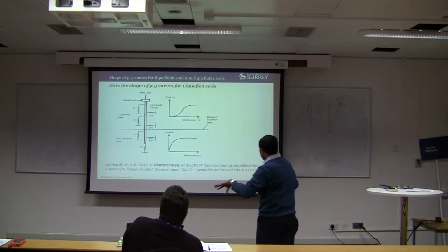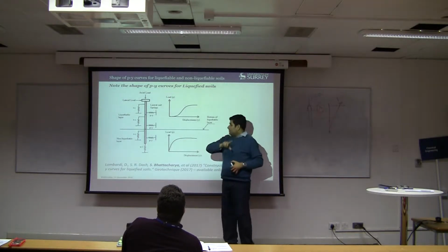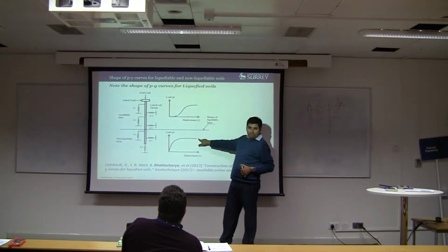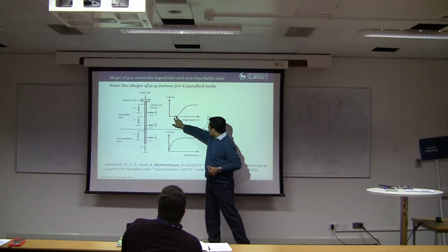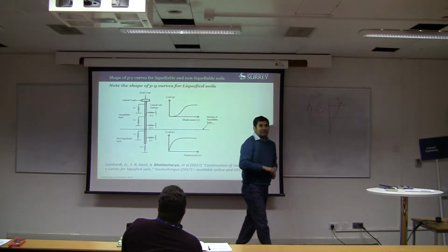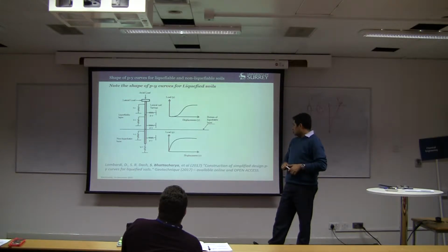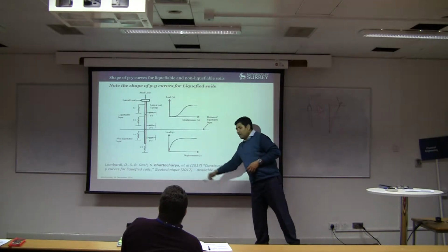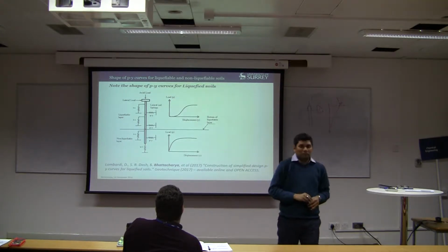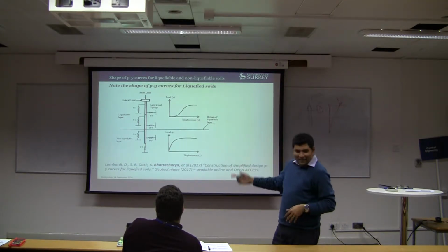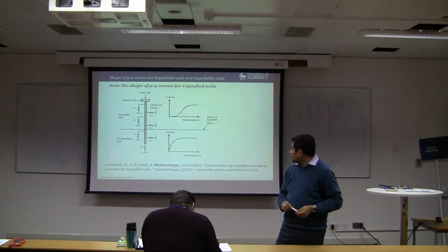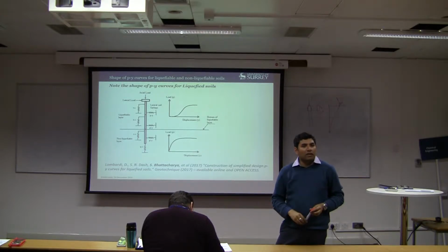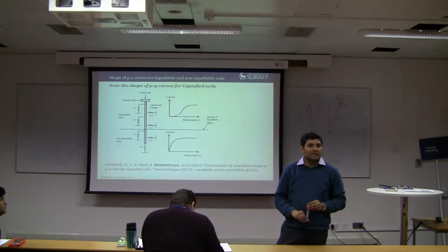Because there is water, right? So what it is, in a normal condition, the springs look like that form, but when it liquefies, the spring takes this sort of shape. So that's the point where you have no resistance, right? This is a very, very advanced analysis. So this is a 2017 article. So you can just basically remind, the code will take a few years to bring into account and update all these things. So these are just to remember, if you can get a project to work on this thing, I think actually I will use the updated research.